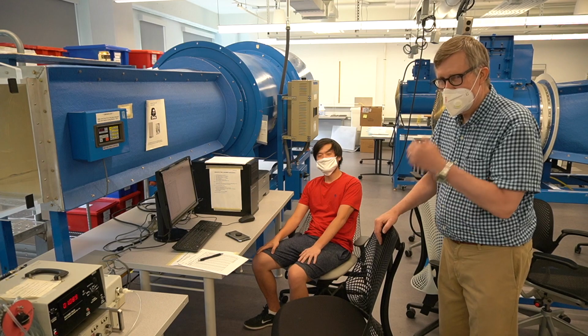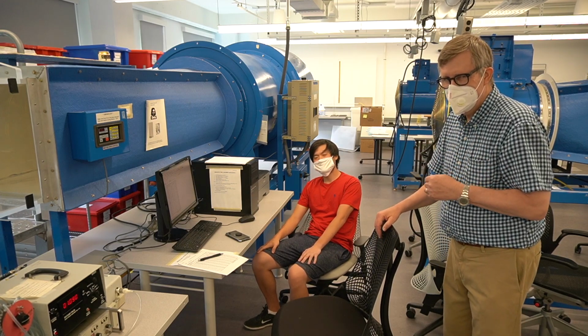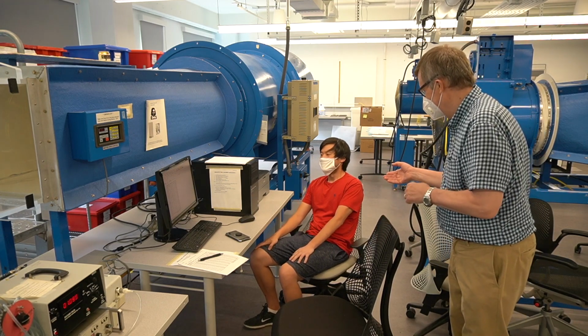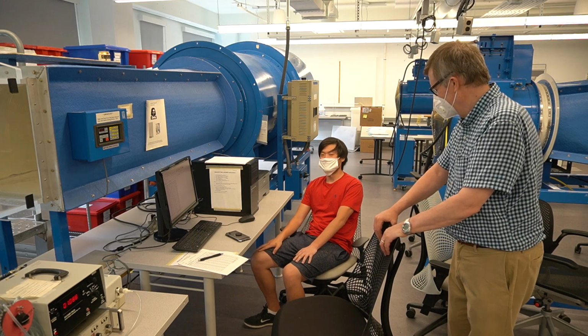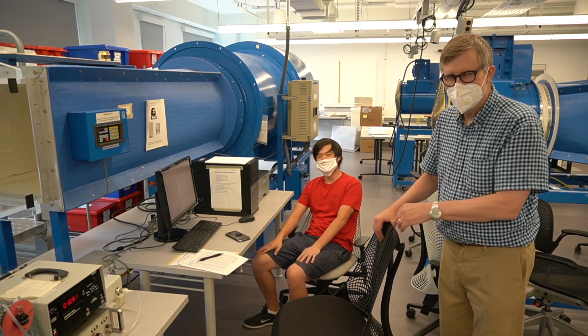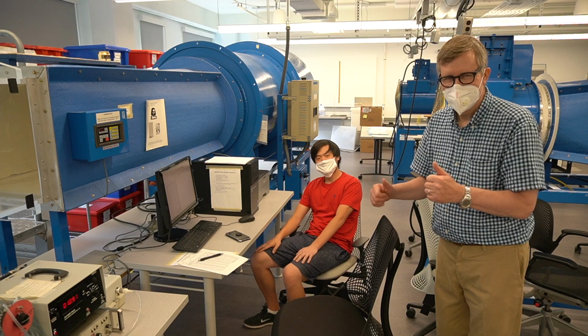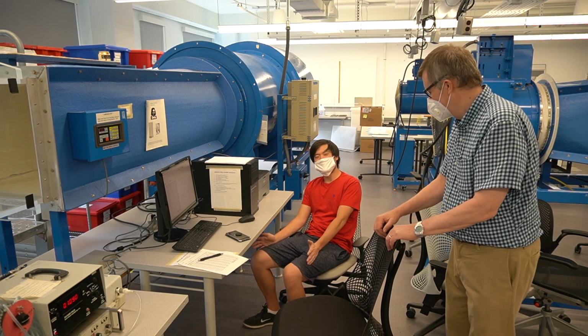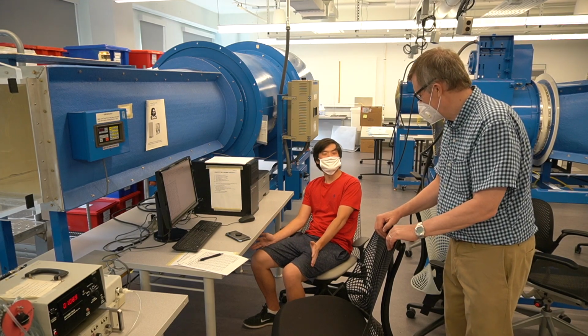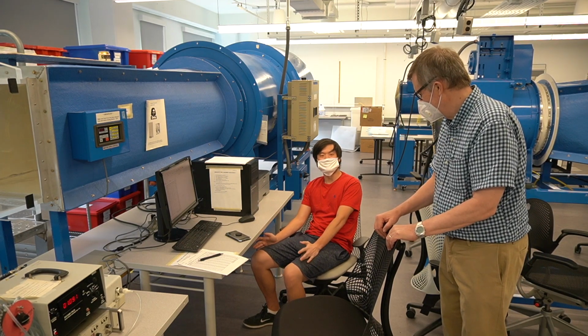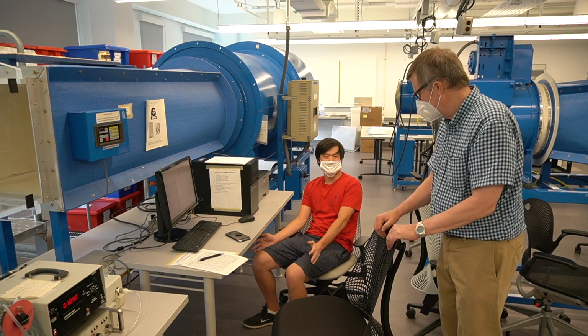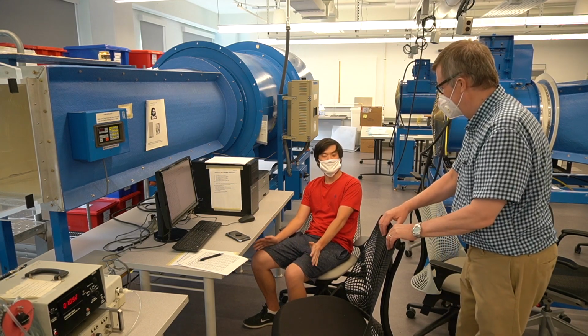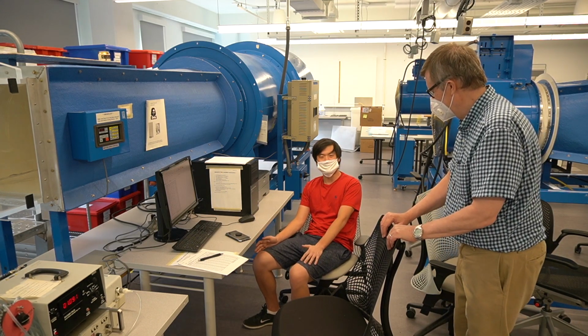So what does that mean about the pressure on the front face of the cylinder compared to the back face of the cylinder? The pressure on the front face of the cylinder must be less than the pressure on the back face of the cylinder. But how could that be? We must be in the cavity mode, and the recirculating vortices in the cavity mode must be stronger than the vortices on the back of the cylinder, creating stronger negative suction on the front than on the back.